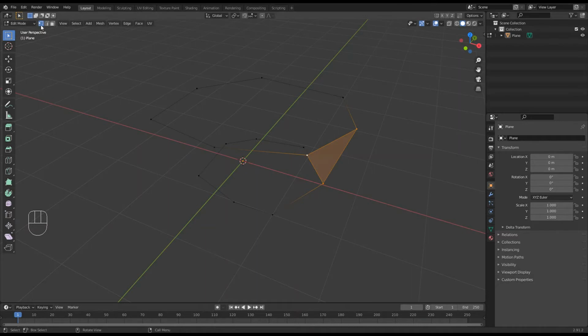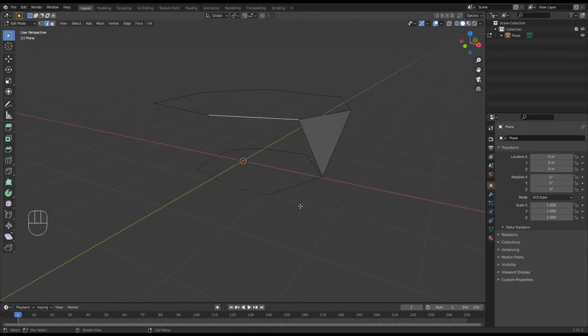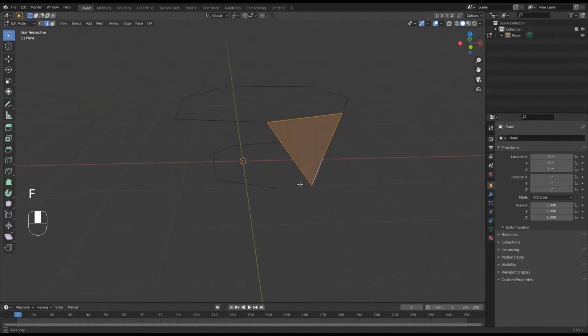And so there are actually selection keys up here. So we've been working with the vertices. If I hold over there, vertex is selected. If I then go to the next one and click on that, then my left click actually collects the whole line rather than the points. So similarly, you could build a surface. Okay, 1, 2, 3, and then it'll just bridge this across here automatically. So again, F for fill, and there we are.